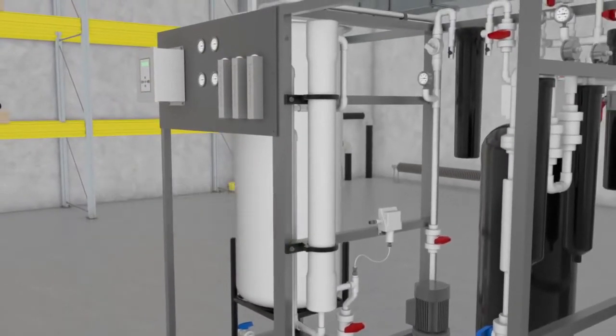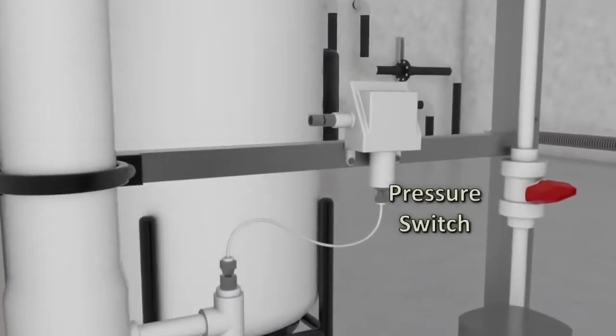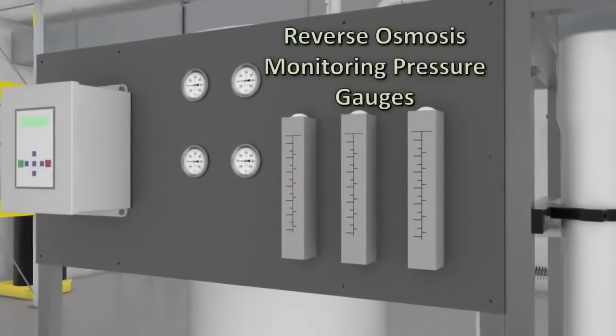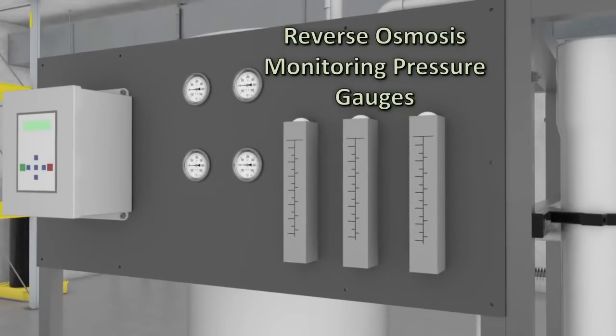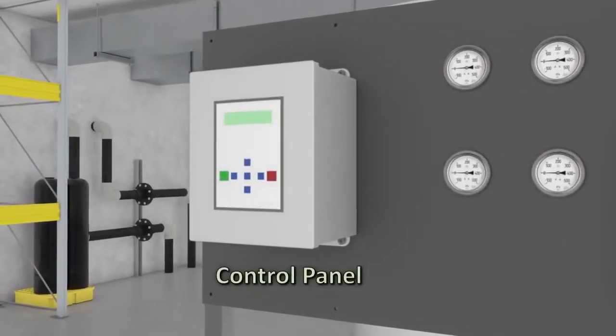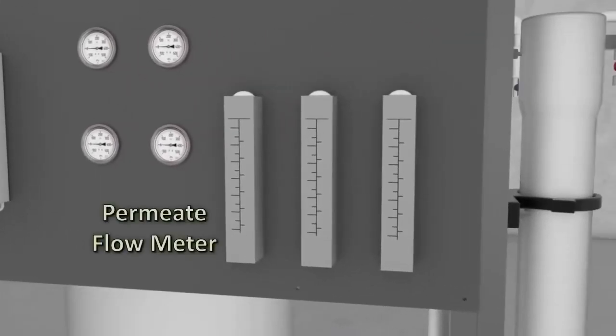As the water passes through the RO membrane, there is a low pressure switch to protect the pump against low inlet flow or pressure. There are panel-mounted pressure gauges to monitor the pre-treatment and reverse osmosis inlet and outlet pressures. The neighboring control panel is used to monitor water quality and facilitate operational functions. There are 3 streams that exit the reverse osmosis process.